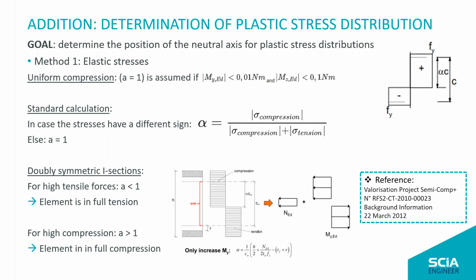Why? Because we will only increase the moment inside the section to reach the full capacity, whereas for an actual plastic calculation, we should increase both the moment and the normal force to reach the maximum capacity.